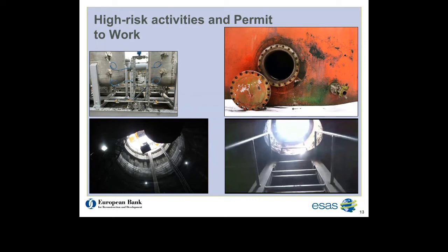Workers are just issued with dust masks. And there is no constant supervision from outside of the confined space. Furthermore, no specialist training is provided for those working in the confined space, nor is there any kind of health screening for those people who are working in this potentially hazardous and difficult to escape from environment. Additionally, there is no rescue equipment to effect a rescue, such as winches, harnesses, or a stretcher. And there is a lack of a dedicated communication system between those working within and outside of the confined space.